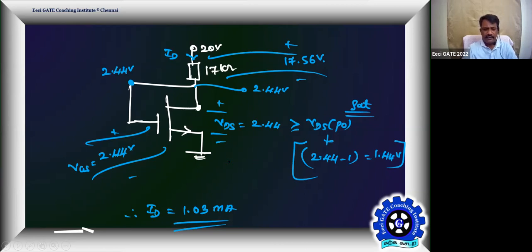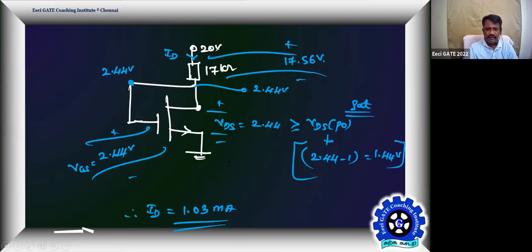Then how to verify this current? So then you have the equation. That's a way to verify. If you don't believe it, this is another way. What we have done is the circuit way. This is the MOS way. Using the MOS characteristics, we know ID equal to, for the given VGS, Kn into VGS minus V threshold of NMOS, the whole square. This is simple. The device is in saturation.